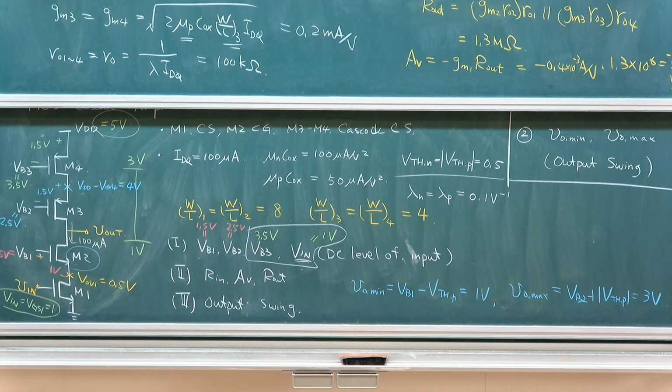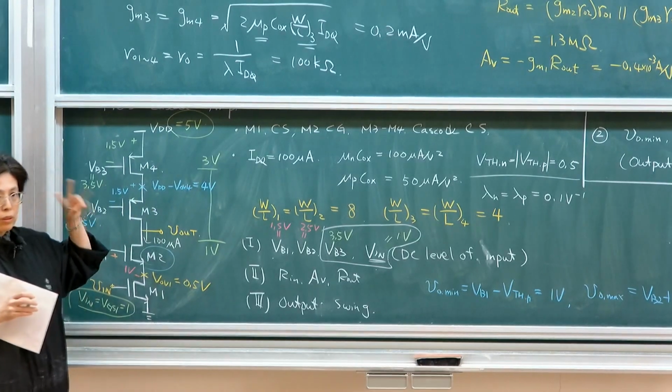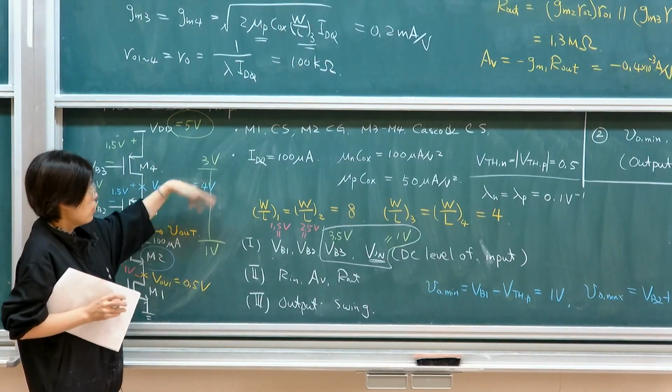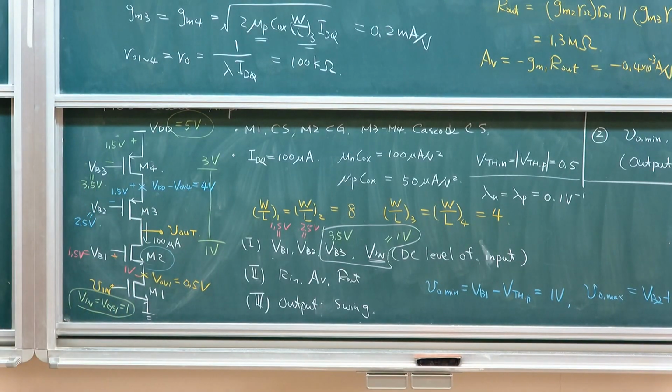So you start with rail to rail. Remember what rail to rail means. Rail to rail meaning the whole stage is 0 to 5. I have 5 volts, but I only have 2 volts margin to move. So only 40%. So that's the main challenge of Cascode structures,